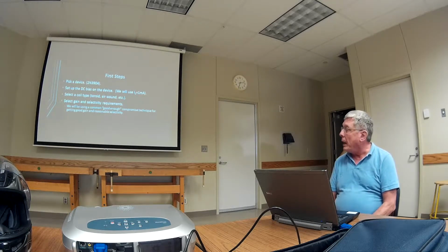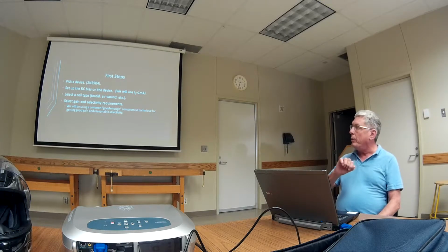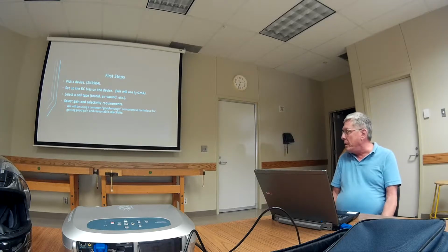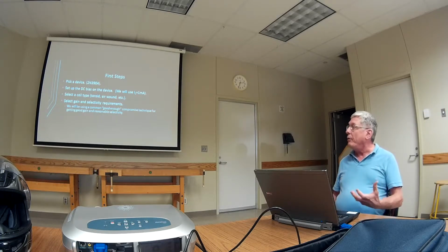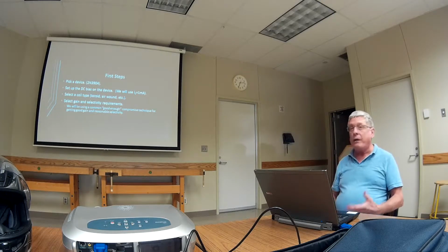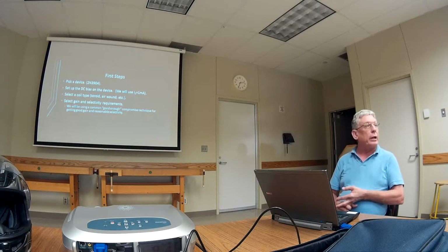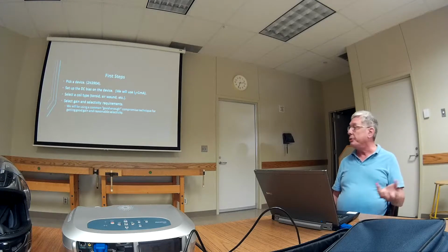Coil type. Lately, I've been headed more towards slug-tuned coils because I like the ability to adjust the inductance to a real fine degree. But a lot of these experiments were done with toroids as well. We need some idea of how much gain or selectivity we want. And what I'm going to show you is something that works well for me that's kind of a compromise. You get decent gain, you get predictable selectivity, and if you need more of either, you just have to build more stages.